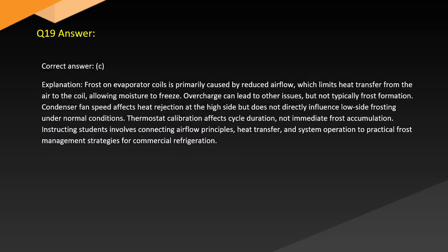Answer. Correct answer: C. Explanation. Frost on evaporator coils is primarily caused by reduced airflow, which limits heat transfer from the air to the coil, allowing moisture to freeze. Overcharge can lead to other issues, but not typically frost formation.